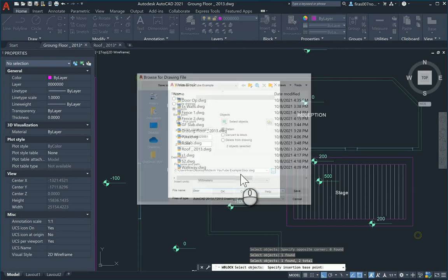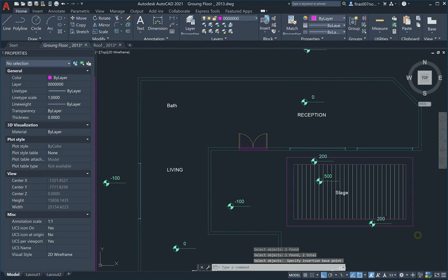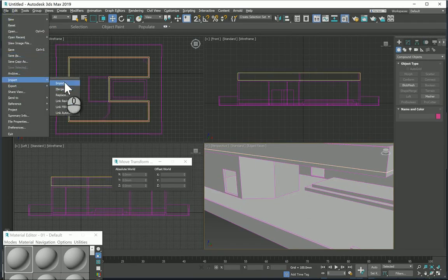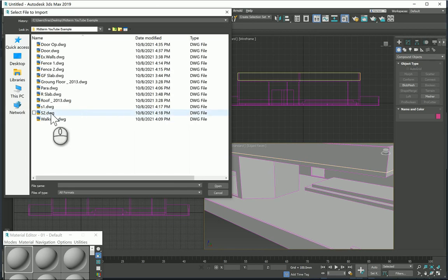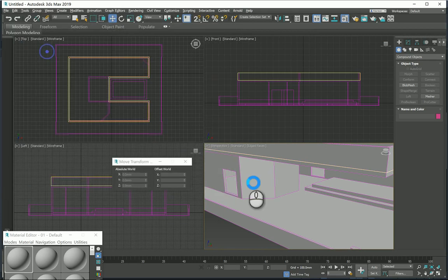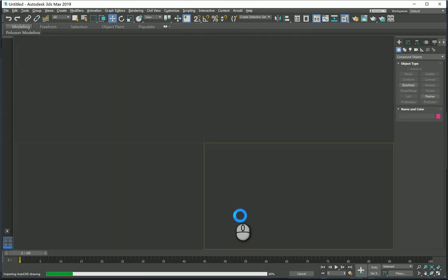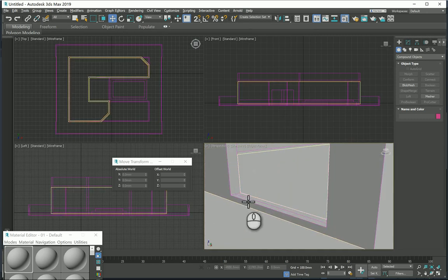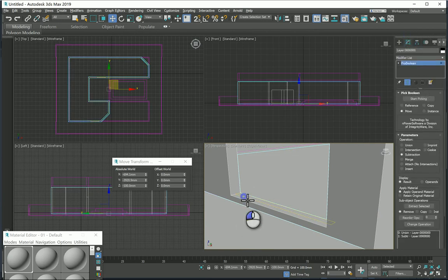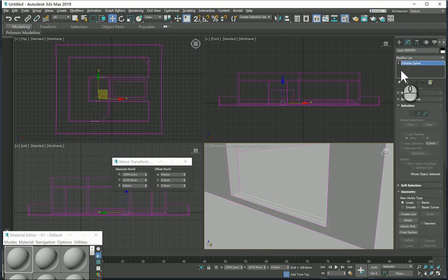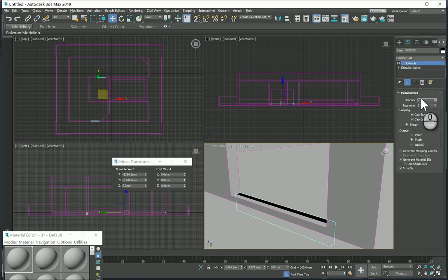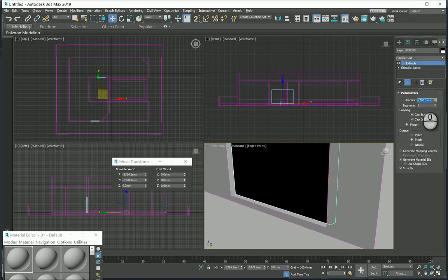All right, same setting. So the Z value will be 0 and the extrude amount will be 2200. Shift and Z to get back to the same previous view. Select that. Make sure your eyes are on the modify panel to see what you are selecting. You need to see here editable spline, and voila, we caught it. Get rid of this, make it 2200.